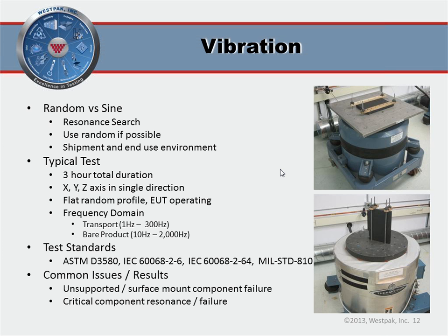So what we're really looking for, again, is the resonances of various critical components in the product. We're looking at the frequency at which those resonate, and also the amplitude. It's a very important indicator of the damping built into the product. Both of these are very important for the ongoing quality of the product, but mostly for transportation-related stuff. Consider this, that unless your customer's next door, as I mentioned before, you're going to be shipping something, and it might be shipping for half a world.